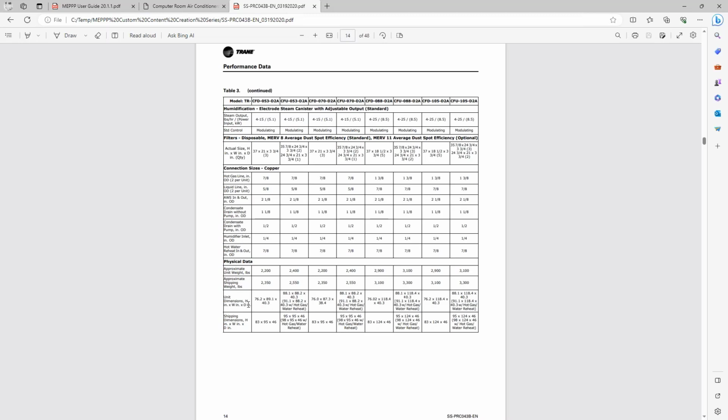As you can see, the unit dimensions are specified height in inches, width in inches, depth in inches. That's how this manufacturer specs and documents this. So even if you are metric, you'd want to still use inches in this case because that's what you can order it as. You want those sizes accurate. Everything inside of here is spec'd in inches, the filters are inches, everything is inches. I'm going to make one quick modification to my family, and that is I want all of my length values to be spec'd in inches because it's going to save me from accidentally typing in 88.1, forgetting to put the inch mark, and ending up with a unit that's 88.1 feet.